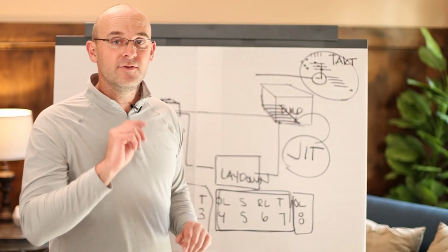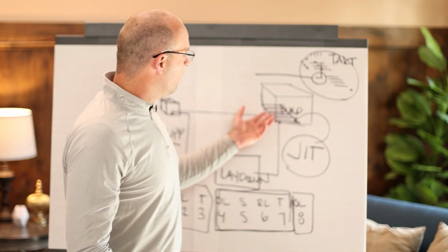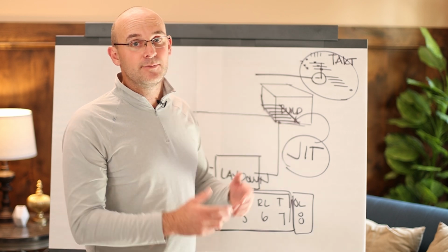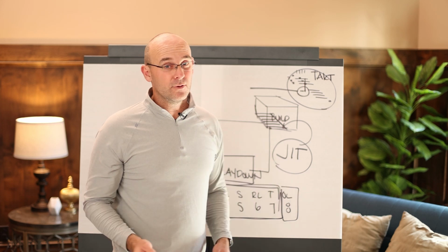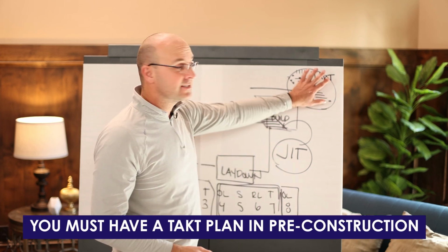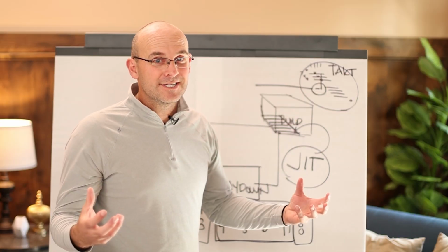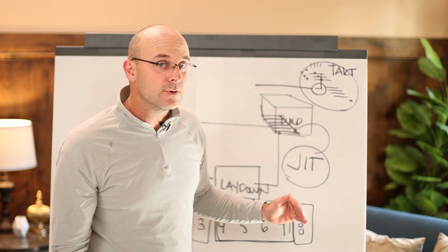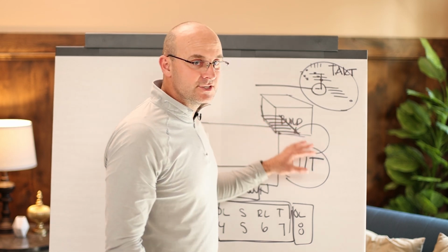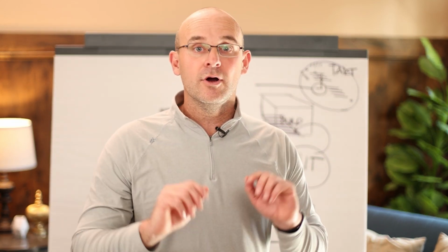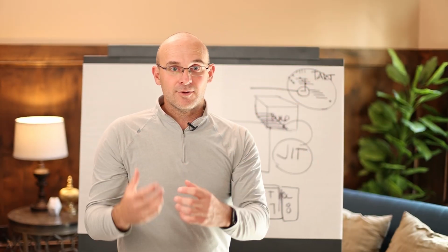Let me give you one example. Sometimes people ask, well, if you're doing just-in-time deliveries, what about the door frame contractor that needs to bring it all out at once? What about the duct supplier that wants to load the whole floor? The answer is we must have this tack plan in pre-construction and really break that project up by zones and buy it out so that the deliveries come to the laydown or the place of work by zone and not according to the whole floor or the whole building all at once, so that we can bring those materials out zone by zone just in time.